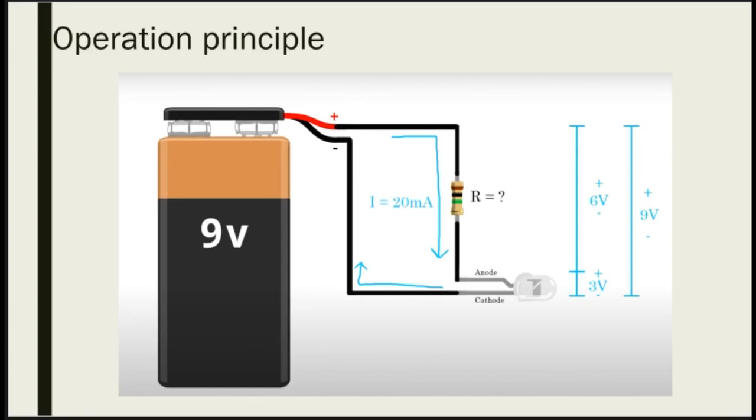So to find the resistor. Yes. Okay. By the way, do you already have the color code for the resistor? Okay, that's fine. But do you always trust 100% the color code? I would say probably not all the time, for a couple of reasons. Sometimes you can look at the color and not be sure if it's, for example, orange or red, right? Because maybe it's been a long time and these colors have changed colors. So you can't trust it.